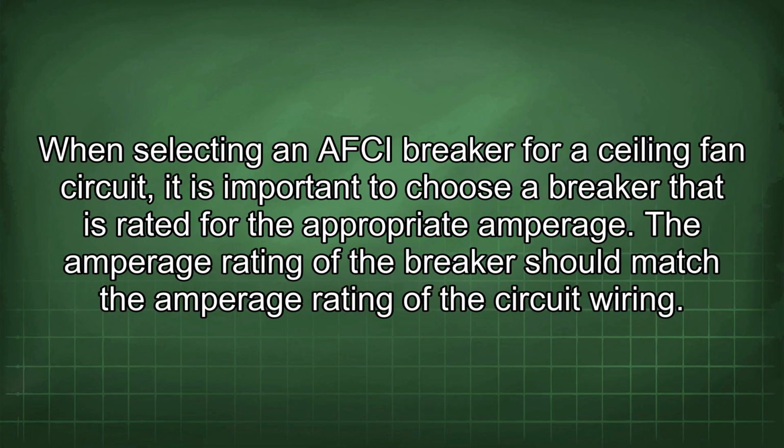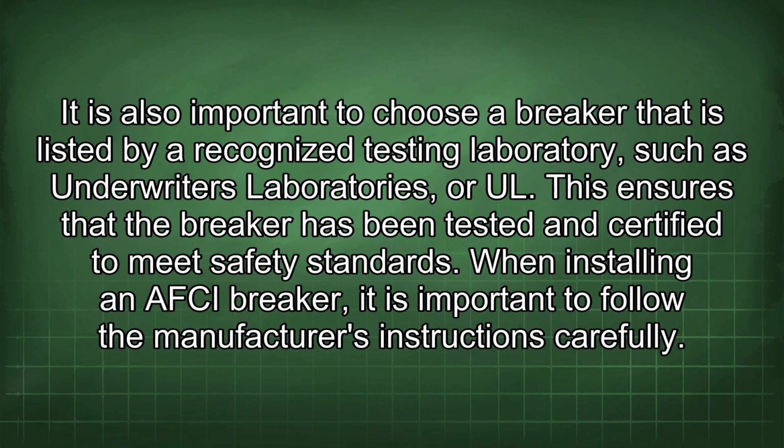When selecting an AFCI breaker for a ceiling fan circuit, it is important to choose a breaker that is rated for the appropriate amperage. The amperage rating of the breaker should match the amperage rating of the circuit wiring. It is also important to choose a breaker that is listed by a recognized testing laboratory such as Underwriters Laboratories, or UL. This ensures that the breaker has been tested and certified to meet safety standards.